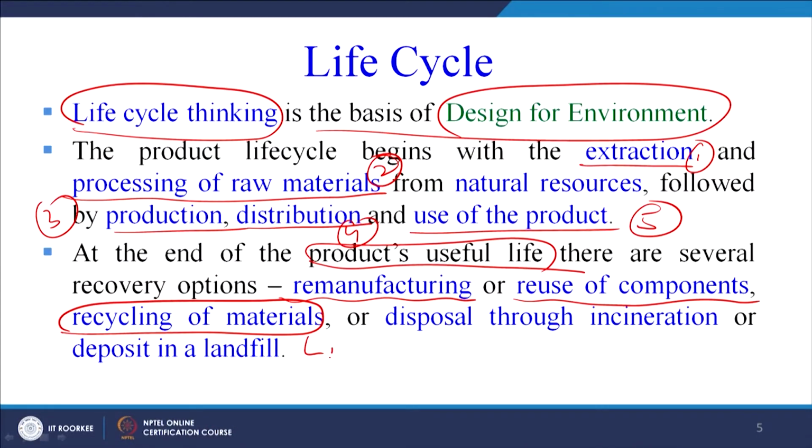This is important from the DFE point of view: when we are designing a product, we must try to choose materials which are recyclable. Many times we choose materials which are non-recyclable, which have to be burnt or put under the land for landfilling. That type of material we must avoid when designing our product, as per the design for environment guideline, that we must use materials which can be recycled or disposed of through incineration.